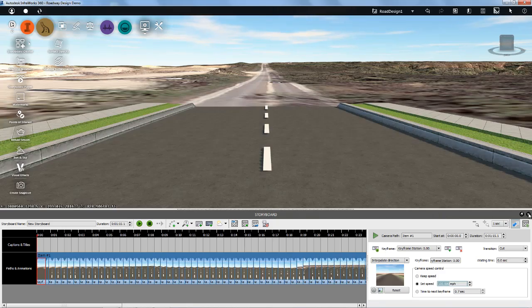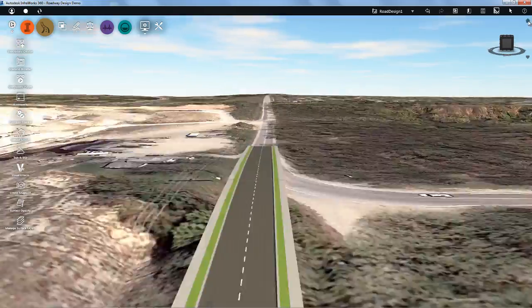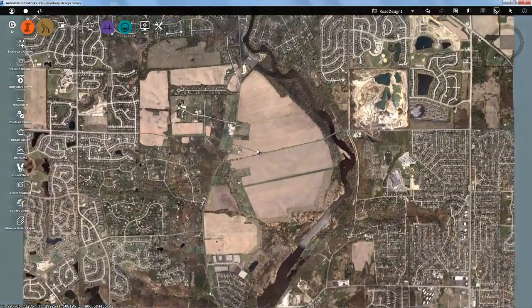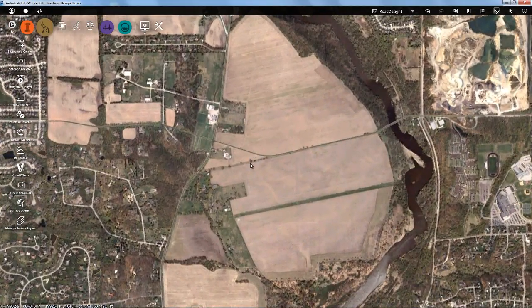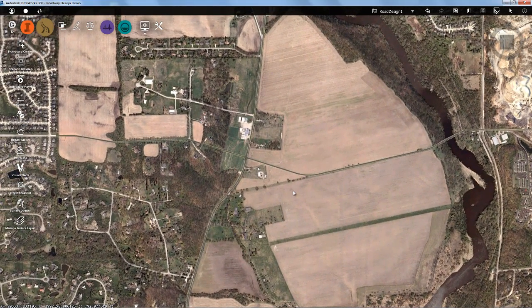At this point, I am pretty pleased with where my roadway project stands and would next like to get a rough estimate as to the earthwork required for the improvements. Remember, there was a fair amount of cut on the west side, and I am interested to see if I am anywhere close to balancing. After making this determination, if necessary, I can further refine my roadway concept. To determine this value, I will have the system calculate some rough terrain statistics. Essentially, this tool was designed to calculate the changes to the existing terrain as a result of my improvements.